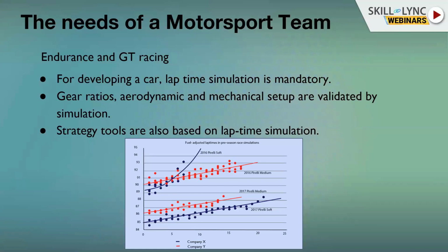And also you can add, for example, a tire model on your lap time simulation to see the effect of the grip lowering lap after lap, and that's why it's also more and more used in GT racing, to be able to have a race setup which is low on tire wear, and a quali setup which is high performance but high wear.